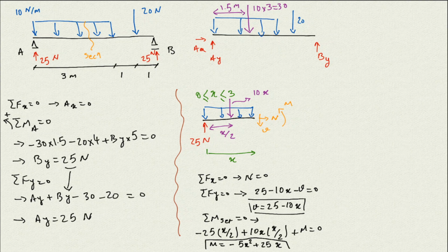So we can, in that section, then we need to go to the next section and start to do the same thing for the next section again. Then look at the next section. So between, that was the first section. If you have distributed load, we need to have one section in that distributed load. Then between every two sets of load, so there's one set and there's another set, we have our second section is going to be here. So it's going to be our section 2.